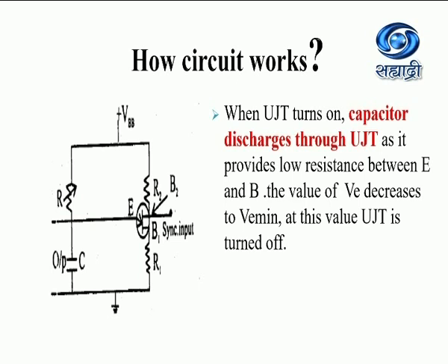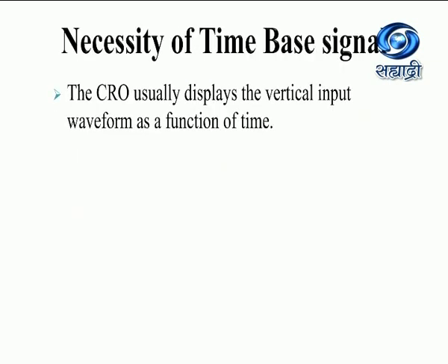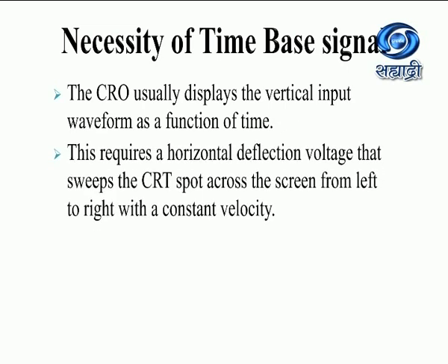So by using this switching action, we will produce the charging and discharging process of the capacitor, and we will get the sawtooth waveform across the capacitor, and hence this cycle produces a sawtooth waveform. Necessity of time-based signal. Why is this time-based signal required in the CRO?